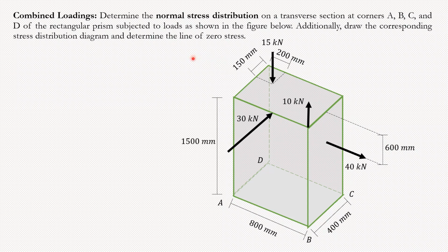As I mentioned, we have axial stress. In this case, the normal stresses that we are discussing are axial stresses and flexural stresses. And as you can imagine, axial stress, like a column, can be applied right in the middle like that. And flexural stress can be about both axes here, right? Again, we don't have the y axis here, so we're going to discuss all of these axes later, but we don't have twisting, that's like shear, so we're not really concerned about that. The only axes we are concerned with in this case are this axis maybe, and this axis. So we're going to go through the steps and how we can make the question easy for ourselves. Okay, so let's move on.